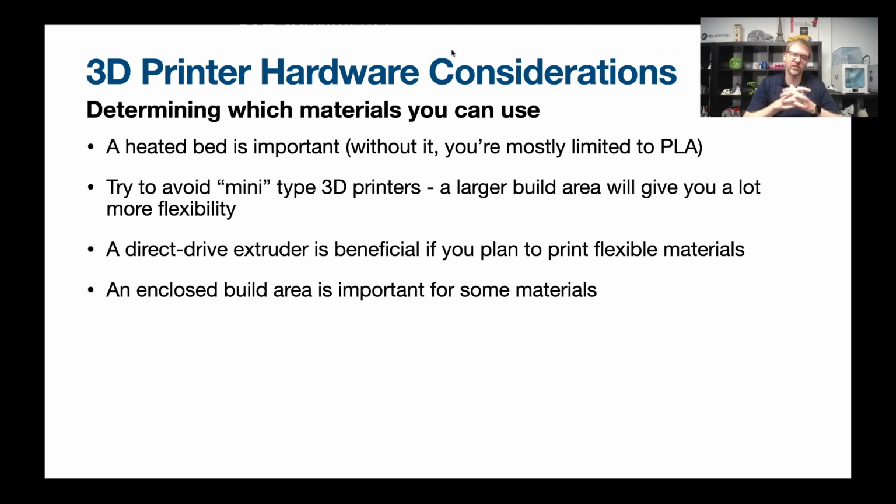Really depends on what materials you're going to use. Some of the more advanced materials have a tendency to warp, and they'll tend to kind of lift off the build plate, especially at the corners, and having an enclosed build environment that'll keep that build area warmer makes all the difference in the world. Having said that, nowadays you have access to some wonderful adhesives that I'm going to touch on later, and those adhesives can also be a great way of dealing with those issues, and you might be able to print some of those materials without an enclosure, even if you might not have been able to without that adhesive. So I'll show you those in a bit.